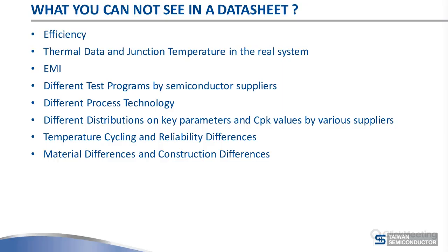The next step we're doing is to see what you cannot see in your datasheet. What is hidden there? The first three things I think everybody will be familiar with. You have to test the efficiency in your design, test the EMI, and you had better also check the junction or the case temperature with a camera to compare two components. So that's straightforward.